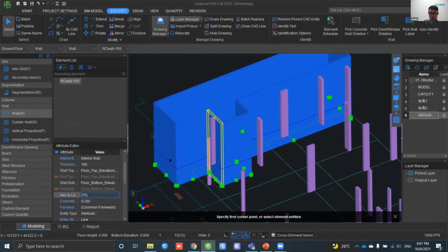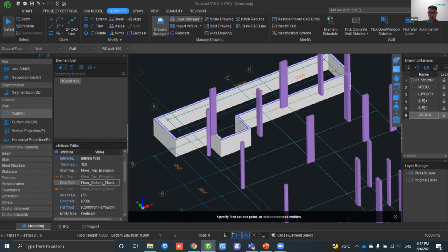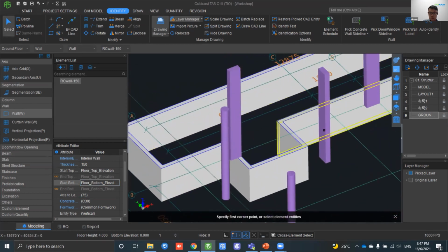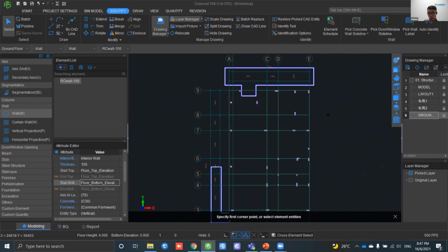So what's left to do is to minus or to remove all of the walls above. So we can actually change this, or we can also directly minus this as well. So the floor height is 4 meters. Oops, sorry about that. So minus 4. Then we have the walls at 1.5 meters deep now. Now, I think we have done most of the structural items.